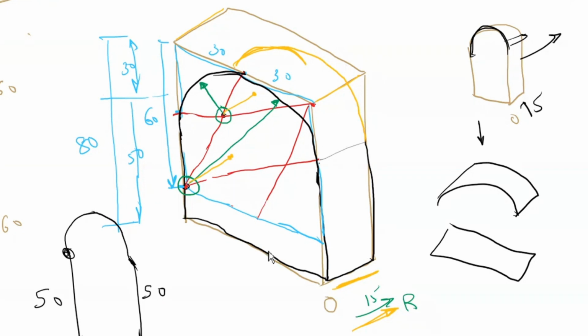For that, what are we doing? We are just moving the center points from this plane, this outer plane, to the plane behind, the plane which is extremely close to us, to the plane which is away from us. Okay, so we are just extending this center. So this center is extended here. What distance? 15 mm. Which direction? This direction, that is parallel to this line.